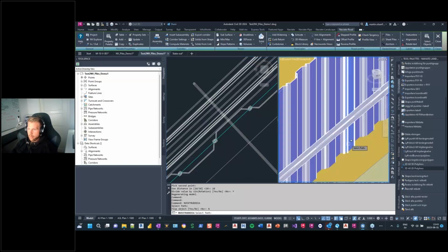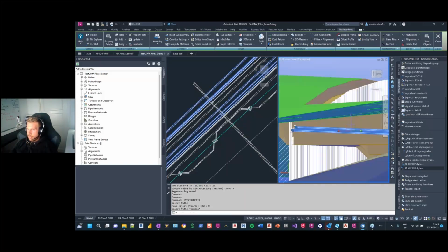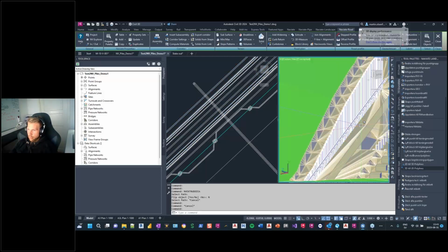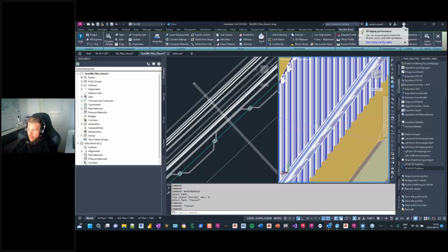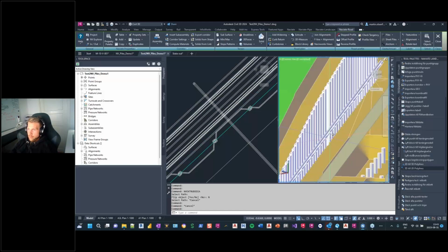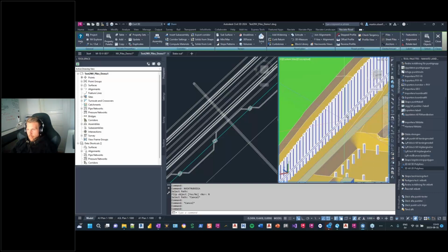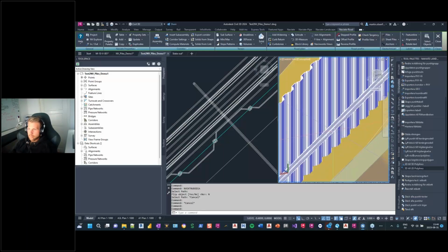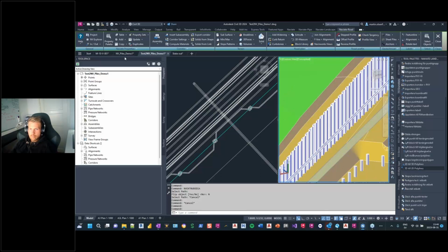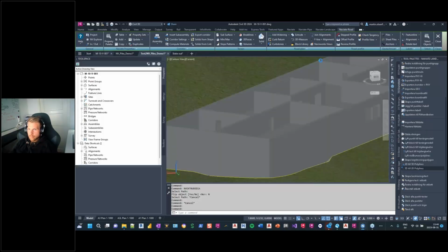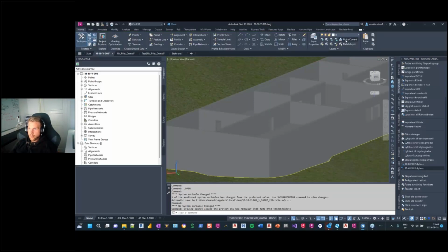And I don't want to flip it. So the second one I get in the right place from the start. It's a little bit hard to see here. So it is the first one that is a little bit tricky, but the second one will go very smooth. And for everyone else you will do now, if you have the same size and the same slope of the anchor, it's going to be the same offset values. So this only needs to be done once per setup of anchor, sheet pile, and walling. Yeah, exactly.